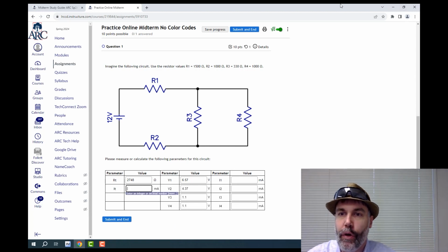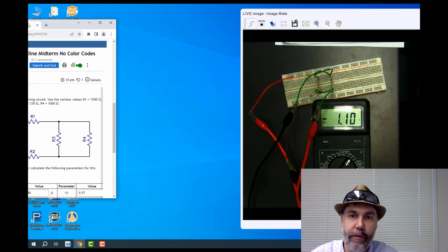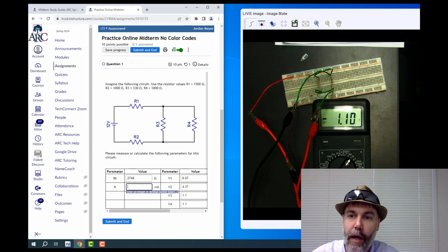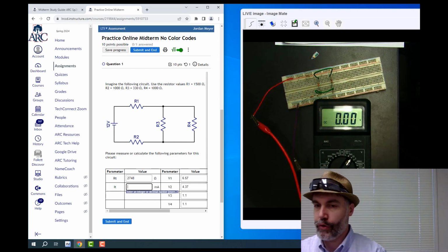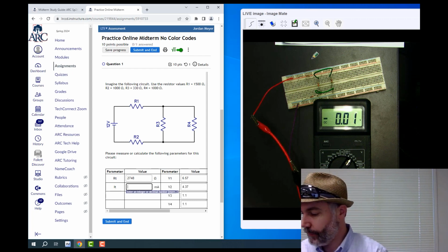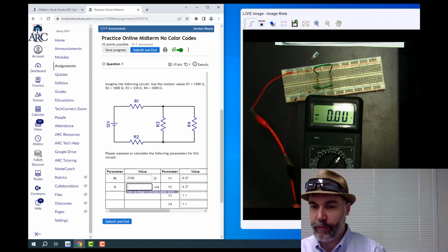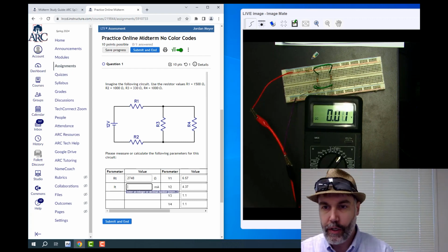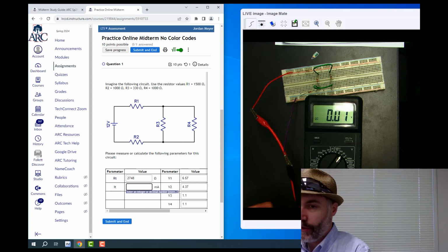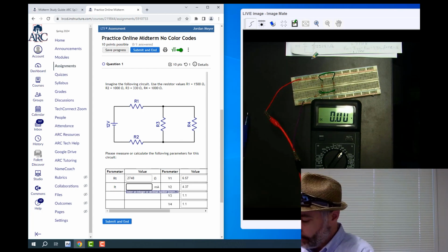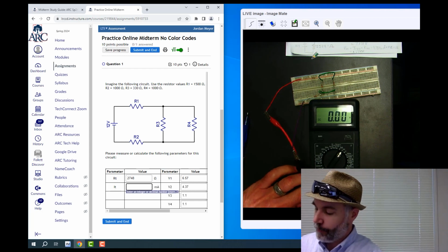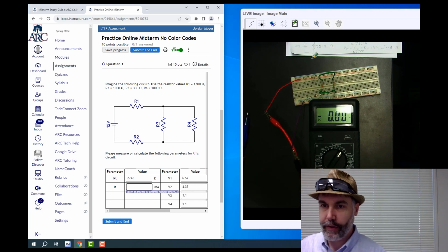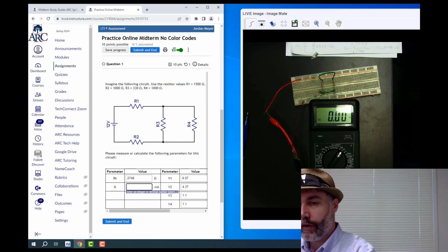And then we're on to our current values. So measuring current is a little bit more tricky. Remember, there's a couple things we have to do. So we have to put the meter in current measuring mode. So that means we have to move this red lead over to this port that says mA for milliamps. Remember, the black lead stays in the common port there.